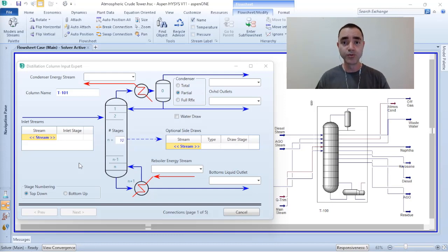So to start with the calculations for sizing and selection, you must have the product specification and the raw material conditions, and you will do the calculations to verify the total number of stages of equilibrium between vapor and liquid of your feed stream to get the required specification of your product based on the conditions of your raw material. And there are many ways to do that.